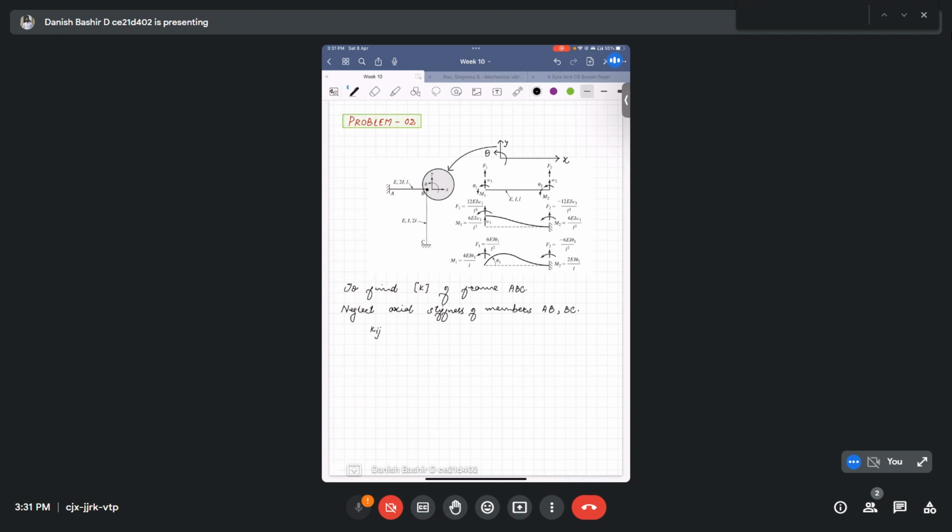So I will again write here for your convenience what i and j denote. It is the force at the ith degree of freedom of the system when there is unit displacement at the jth degree of freedom.